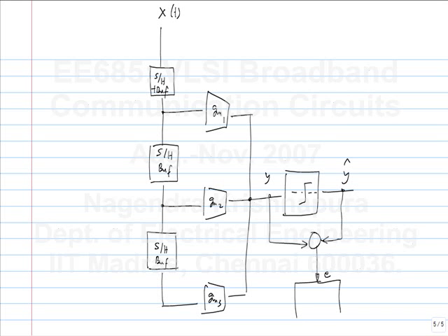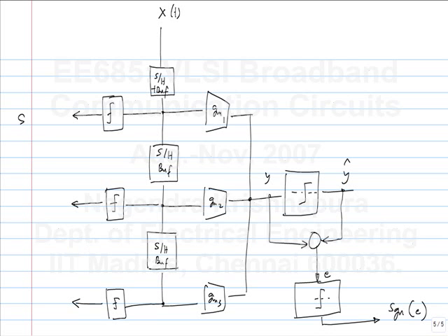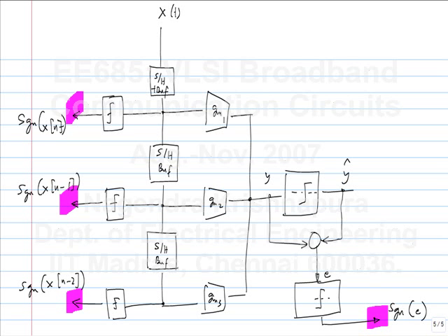In fact, you don't do this. You take the sign of E. And if you had comparators here, you get sign of x of n. So let's say this is xn, xn minus 1, xn minus 2. Using these, I can update GM1, GM2 and GM3. So I take the XOR of this and see whether to decrement or increment this. Similarly for the other two.